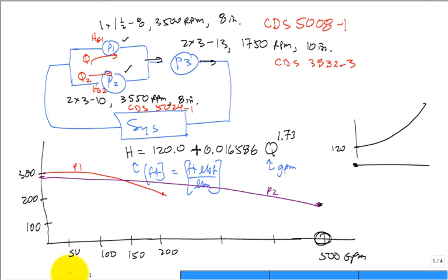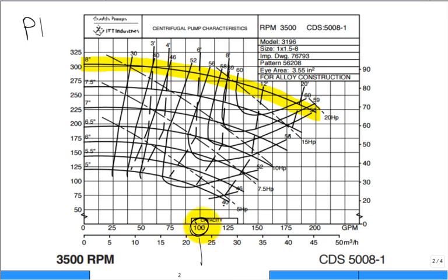Now, you could check that guess and see if it's going to work. Let's just run some numbers by hand. Somebody says, yes, the Q here, let me reuse this illustration right here. Come on now. Erased too much. This Q1 we said was 100 GPM. And this is 200 GPM. Now, let's just go check. At 100, what's the head loss? Or the head gain, sorry, this is a pump, so what number is that?